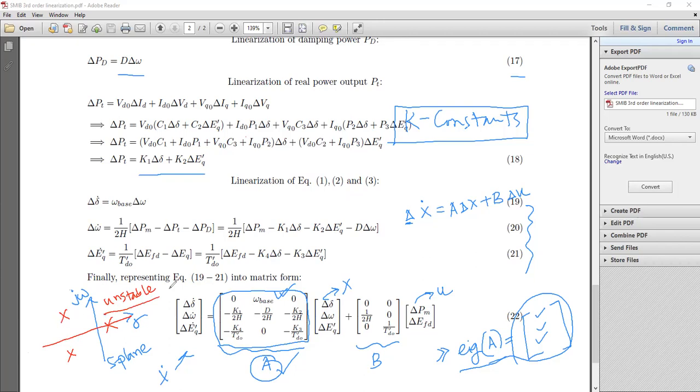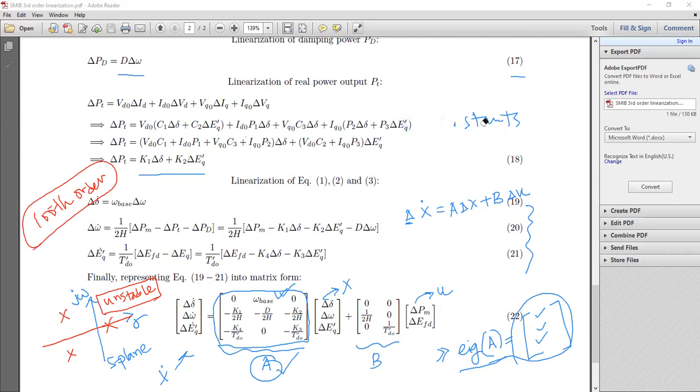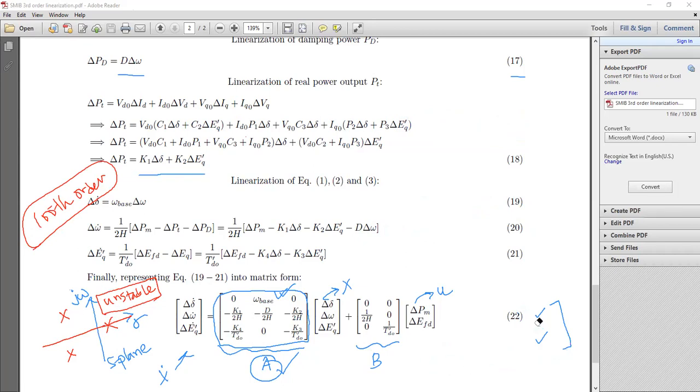So even let's say a 100th order system, this is a third order system, even for a 100th order system, I mean a very big system, even if you have a single pole on the right hand side of the S plane, that is enough to make your system unstable. Can you explain why? A single pole on the right hand side is enough to give you the unbounded or unstable response. Let me give a little glimpse on this because we are running out of time, but I will finish with that.